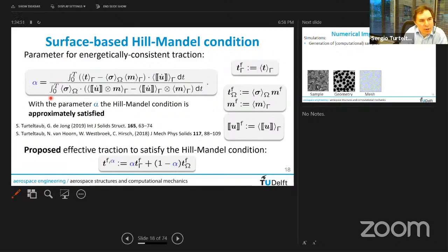Part of the issue is that when we tried other methods, so we tried XFEM as well, but with XFEM, when you have intersecting cracks, it becomes an issue. So for complex crack patterns, which is what we end up having everywhere, the embedded cohesive element approach seemed to be much more robust to handle intersections of cracks. It does require us to embed cohesive elements everywhere, and it automatically creates a numerical issue, which is the artificial compliance coming from the compliance of the cohesive elements.